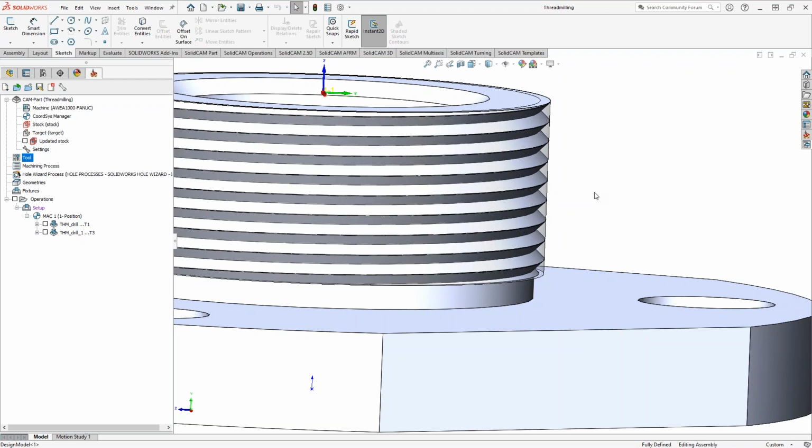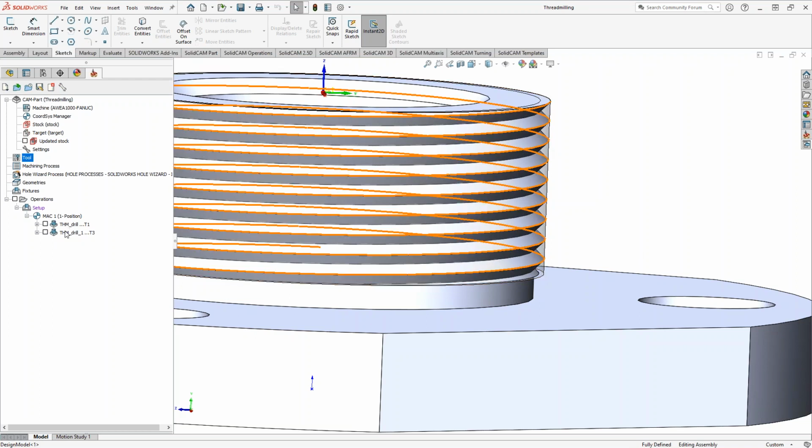When you're doing thread milling, it's the same sort of thing. You're really just generating a thread milling toolpath off of a center point. So this thread is not helping you. It's not a help. It's not really a hindrance either. But I think because you're defining your target off of this model, it's going to think that you've cross-threaded your part. It's going to give you some gouge check issues. And really, that's not what's going on. So I would say this is going to be confusing on the simulation side. I would just get it to be a simple cylinder.